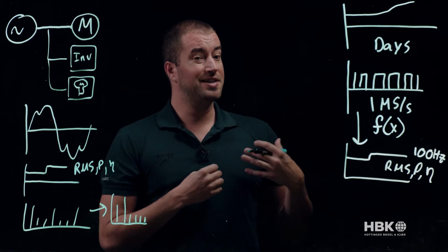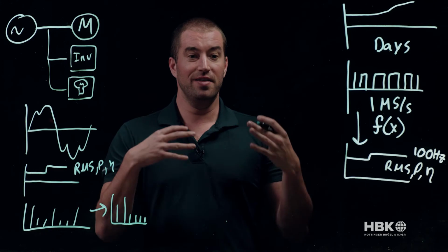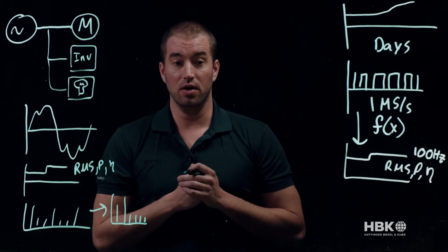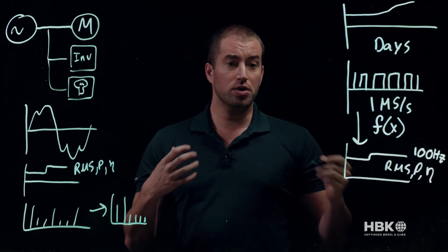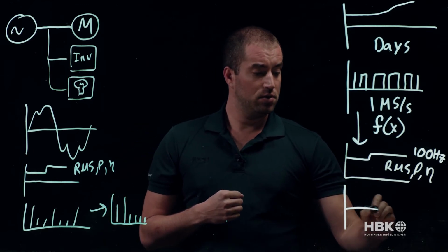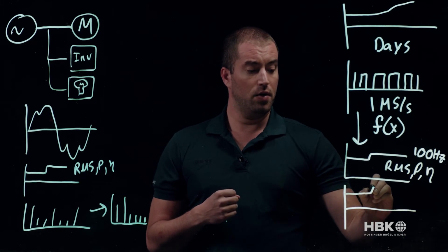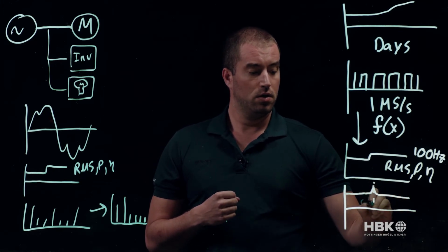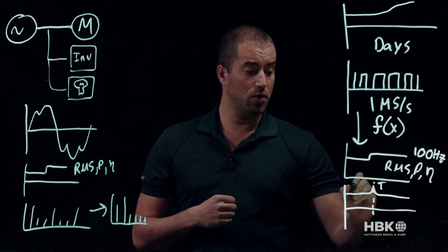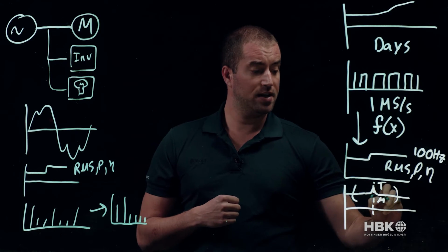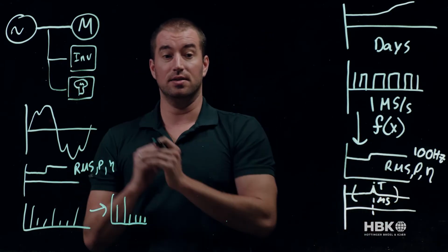Now, another challenge is that we do want to understand how these inverter signals operate. In the event of a traumatic event in the grid, we might want to measure that high sample rate data. Well, fortunately, there are options where when you're measuring, you can monitor a signal, and when you see an event, you can execute a trigger. And this trigger is going to say, okay, I'm going to record megasample data in this short window so that I can take this data back for analysis.